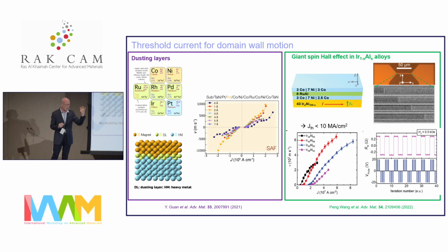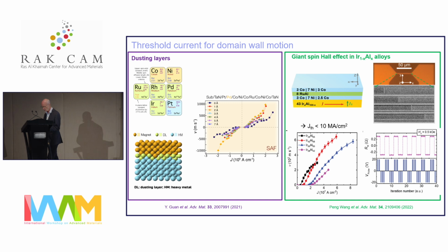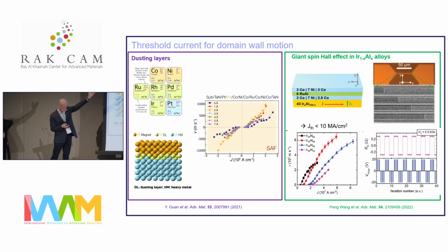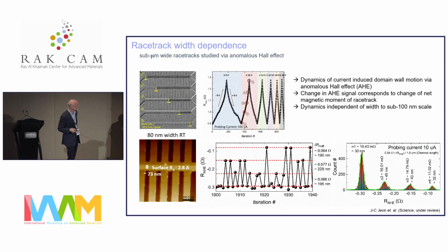So the racetrack itself is basically 1 nanometer thick magnetic material, a ruthenium layer, which is 0.7 nanometers, and another magnetic material, 1 nanometer thick, all combining the layers on the atomic scale, which we could engineer or try to influence the physics to make the domain walls move more efficiently. And of course, we can move them very efficiently, as shown on the right-hand side.